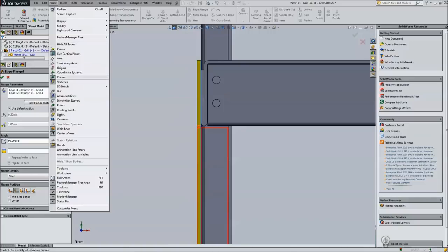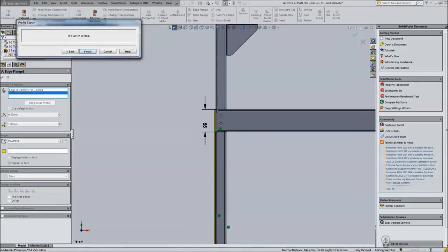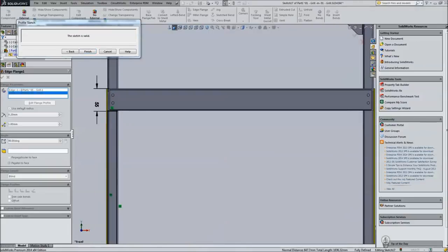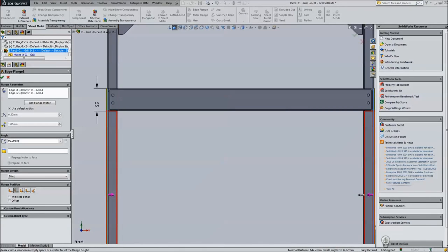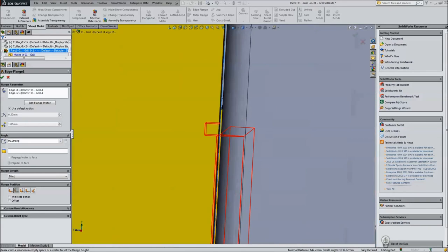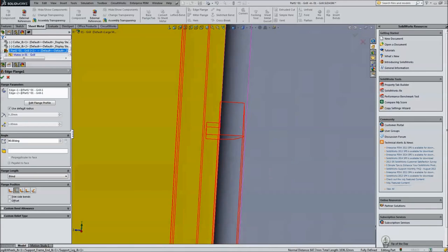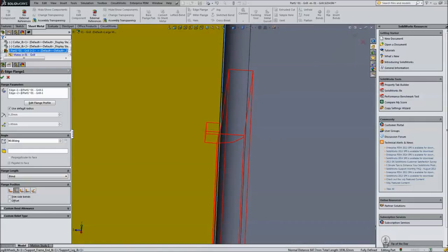So if you go view and sketches is on, all right, we could hide and see it over there depending on the order in which they're at. All right, and then I'm going to rotate it again so I can see which way my material is going. So you can see with the preview here, the material is outside, put material inside. I'm going to hit OK.